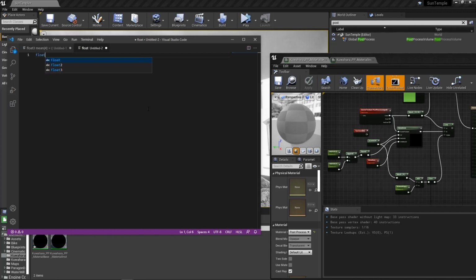So what do we actually need to build the Sobel filter? Well, we're going to start with a gradient x and a gradient y. These are just going to be the values that we're going to store our gradients in, obviously. And we're going to need all the Sobel multiply operations. These are just coming straight from the Wikipedia page. For the x-axis, we're doing -1, -2, -1, 0, 0, 0, 1, 2, 1.